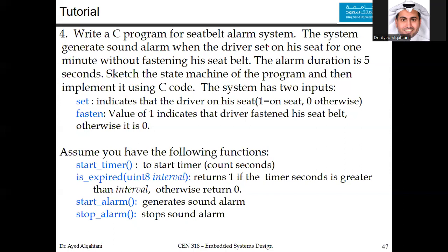Now the alarm duration is only 5 seconds, not like cars right now, where the alarm goes on forever. But here we have a simpler system, so the alarm duration is only 5 seconds. The requirement here is to sketch the state machine of the program and then implement it using C code. And basically, this is the idea of the last tutorial, number 4, to show you that by using the state machine, you will make writing the C code really easy.